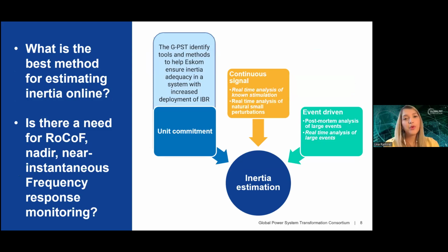Also, it is really important that it is not only about considering in the planning and defining critical inertia and the amount of reserves that we require during the resting period. It is also important in the control room to have awareness of where the system is, what the system conditions are, what the inertia is now and in the future, where the fast frequency response or the response that we are having is, the amount, if it is enough, and also to see if we have a good